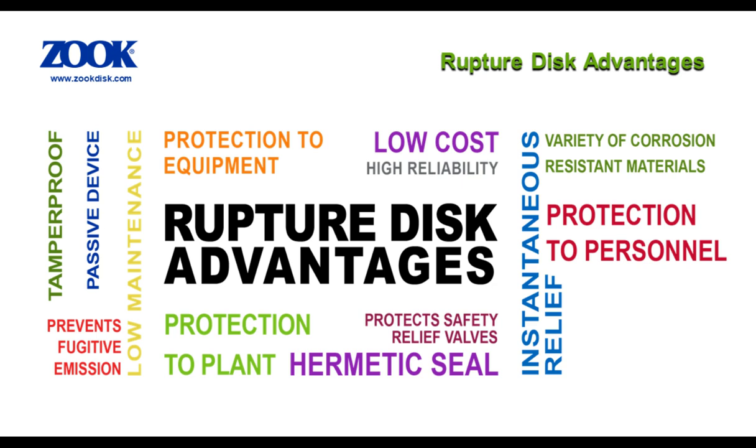Rupture discs provide leak-tight seals and are available in a wide variety of corrosion-resistant materials. Rupture discs are extremely fast-acting, typically going from closed to fully open in less than 3 milliseconds. Rupture discs are zero-maintenance devices with very high reliability. They are a time-tested safety product. Rupture discs are a very effective, low-cost solution to a pressure relief requirement.